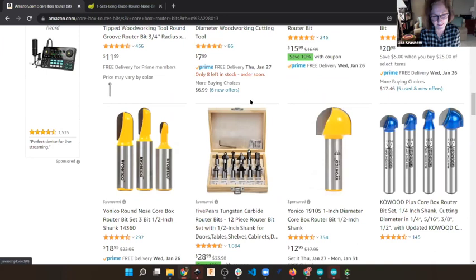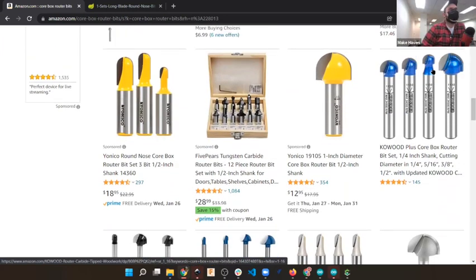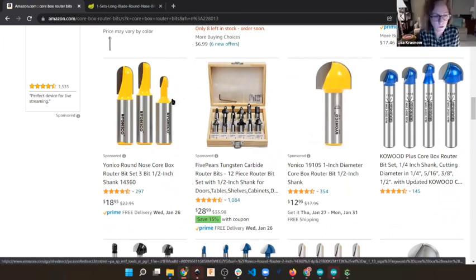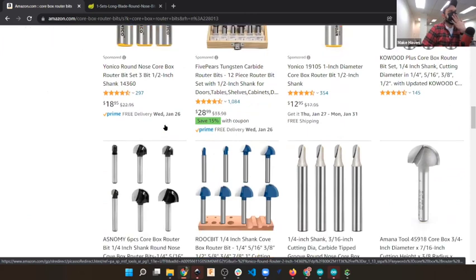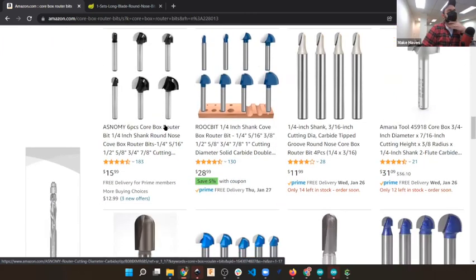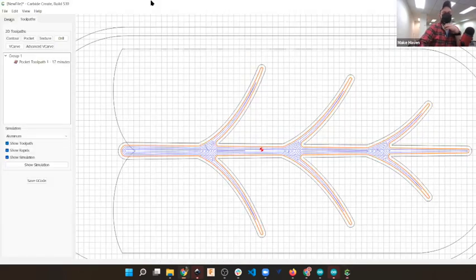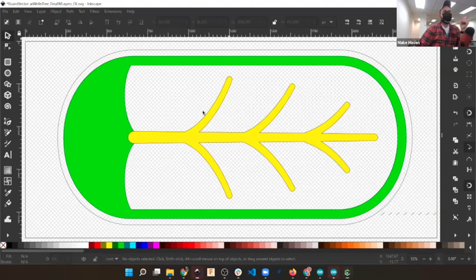Yeah. Just as a note, I do like this style where the cutting head is at least as big as the shank. This one makes me nervous. Oh, right? Sure. Because you can only cut up to that shoulder and then you've got a problem. Right. But if you need a 1/2 inch shank for your particular tool, this is 1/2 inch wide down here. Maybe that's the way to go. Anyways, I am very excited to see how this plays out when you cut your different heights, the yellow at one depth and the green at another.